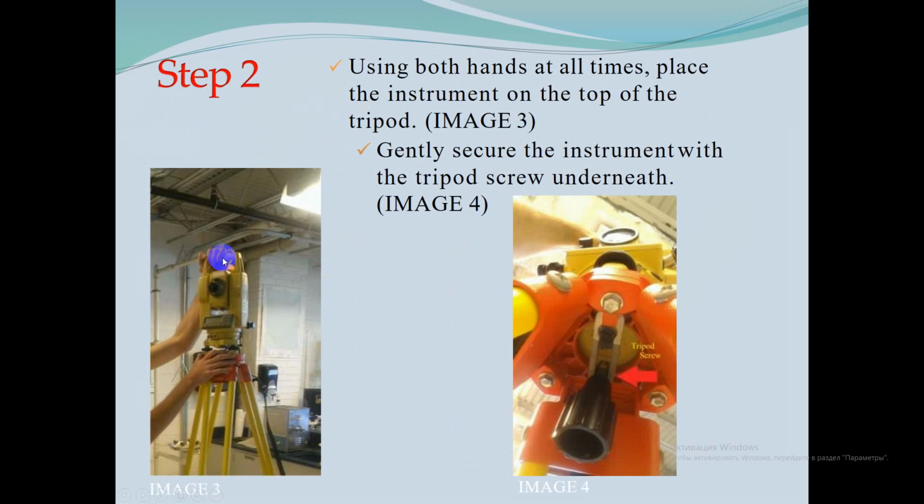Step 2. Using both hands at all times, place the instrument on the top of the tripod. Gently secure the instrument with the tripod screw underneath.